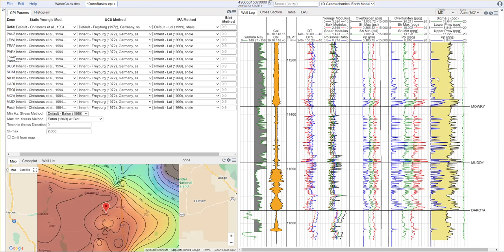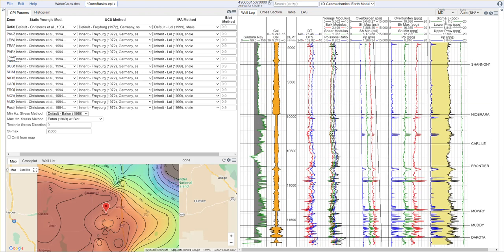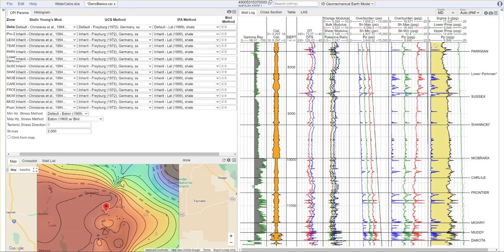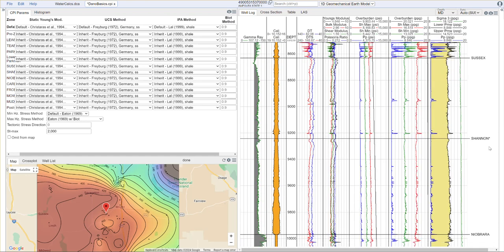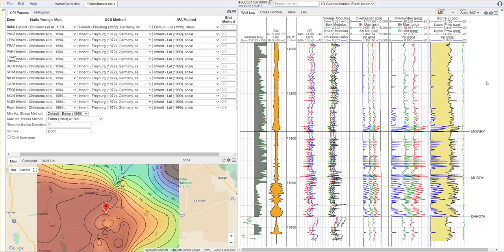These are areas where we often see significant washout, very challenging drilling conditions here, and sure enough, what we see in reality is we generally have quite easy drilling conditions through the shallow part of the section here, and this makes sense because we have some very wide mud weight windows. So we're able to come through here, essentially drilling with normal mud weights, maybe slightly elevated mud weights here.